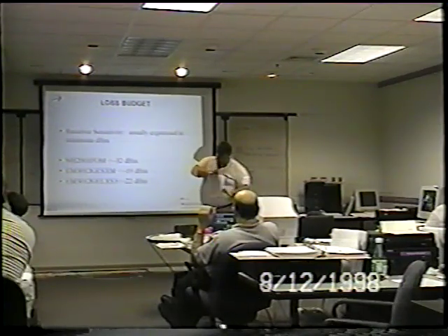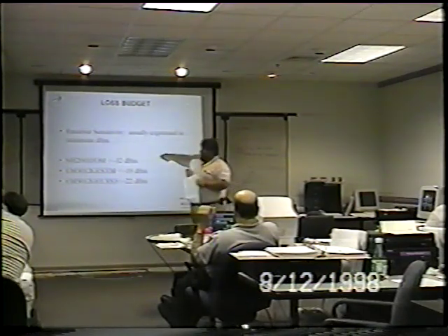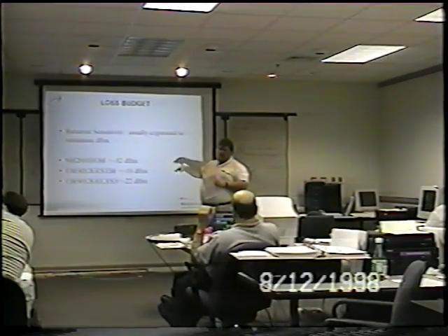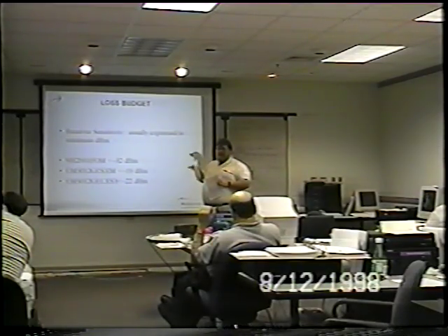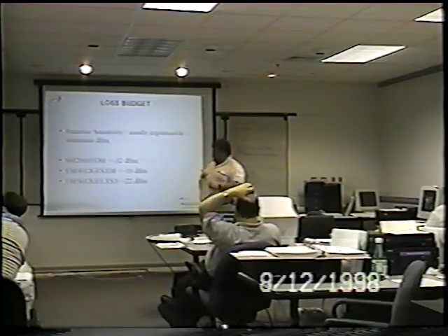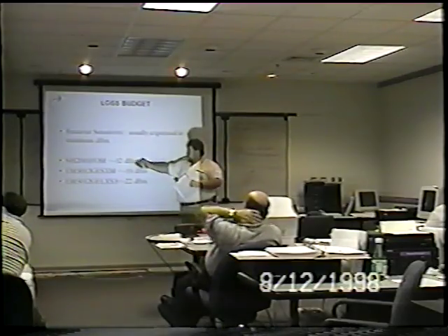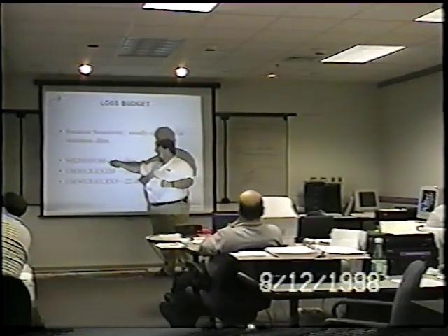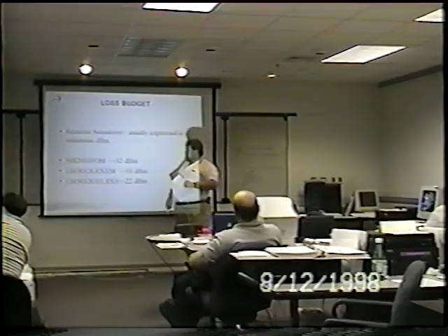Goes over to the right-hand side of the page, that's expressed in dBm, the actual noise floor. This is the minimum amount of light that receiver can detect and decode usable pulses at that receiver. The NH2001 FOM, which is the multi-mode fiber interface, is sensitive down to minus 32 dBm.